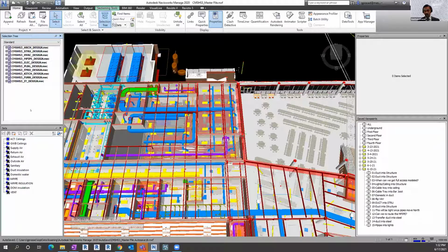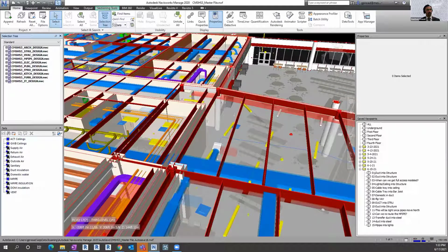So this is where I work with designers and we look at bigger stuff, right? Here's some big things we think are going to cause problems down the road. So how can we get the design to help feed into our coordination and construction process? And we started around 50% DD usually. And what I've done in the past is I go into Navisworks, I look through the models, I say, gosh, I don't like this. I'll create a viewpoint for it, as you can see over here. I number those viewpoints. I create meeting minutes. We discuss the viewpoints. I take notes on each one. After the meeting, I send them the NWD and the meeting minutes, and then they go work on it.